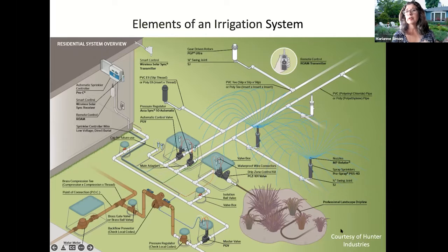Next up is your pressure regulator. So the water comes in from the water provider at a particular pressure. It's measured in pounds per square inch. Oftentimes it can be quite high. Certainly in our work, we've seen 50, 60, even up to 120 PSI in some sections. So crazy, crazy high pressure. Now, sometimes there is a master pressure regulator, and sometimes it is built into the valves themselves. And again, we'll look at that.